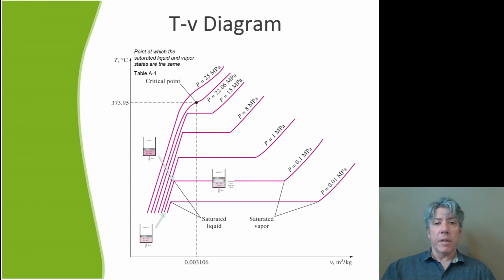And as we add more energy, then more liquid goes to more vapor. So we're moving to the right on this diagram. And of course, what happens is that the specific volume of the system increases. If we're just looking at the total volume of the system divided by the total mass, then that's really what we're plotting here. Now, something that's really important to understand: there are no molecules in there that have the density in the middle of that curve between those two knee points, between the saturated vapor and saturated liquid points.